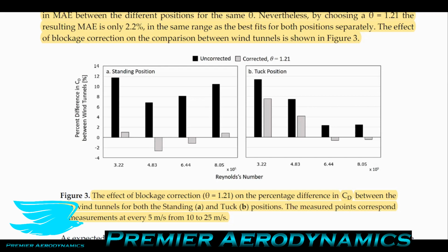And that's because at lower Reynolds numbers, the flow physics is almost always, in almost every application really, there might be some minor exceptions, but generally speaking, at low Reynolds numbers the flow physics is very sensitive to the Reynolds number. When you get to higher Reynolds numbers, the flow physics becomes more robust, which means that the correction factor will be more robust too. And that's what we find here. At higher Reynolds numbers, the errors are within 1%, but at low Reynolds numbers, they're now 5, 6, 7%. So they're even more.